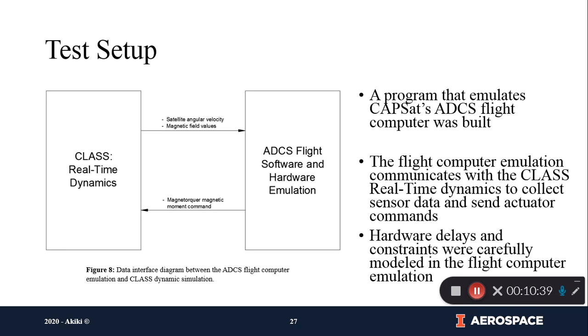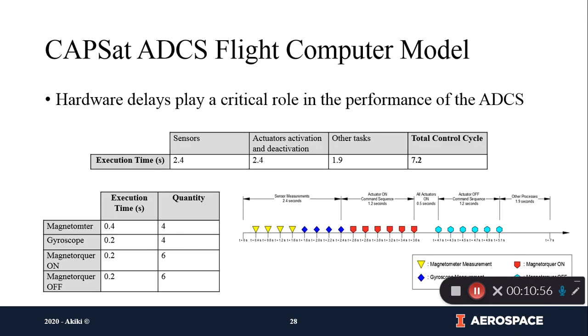The way we set up this test, because the CubeSat ADCS flight computer was not ready yet, we programmed an emulation of this flight computer into the class software, which is a good demonstration of the ease of configuration and flexibility we have with such a closed-loop test system.